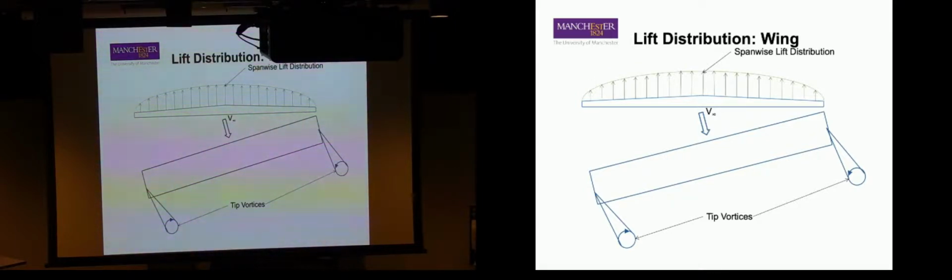How it goes to 0 makes all the difference in the world. The smoother that curve, the more eccentric that ellipse is, that shape, the less differential you have incrementally as you go spanwise. The weaker those tip vortices are, the less induced drag you get. So this term induced drag is the drag induced by the generation of lift on a 3D wing.